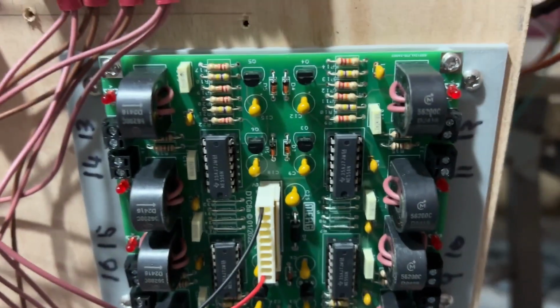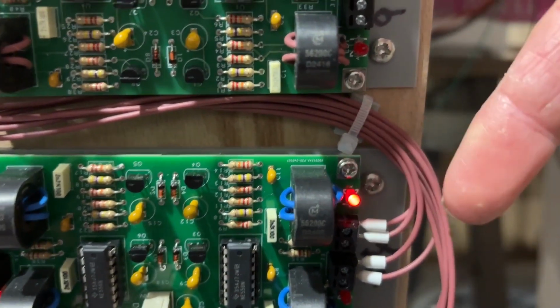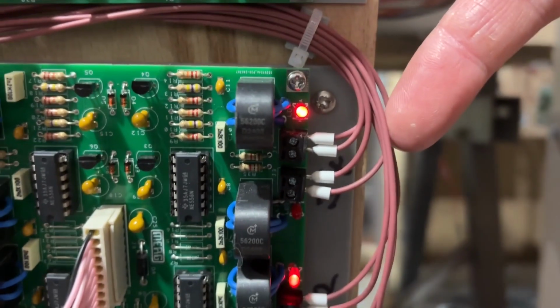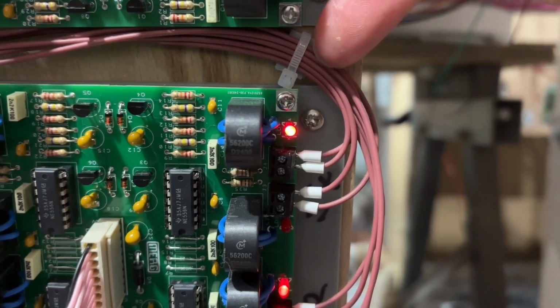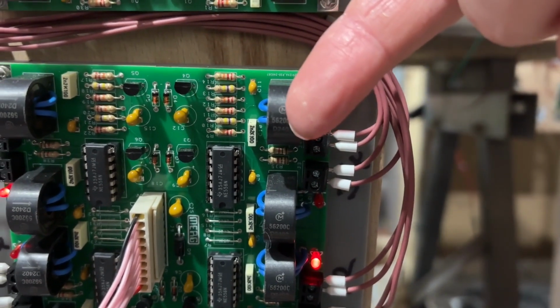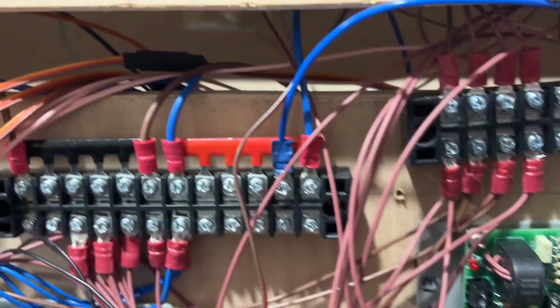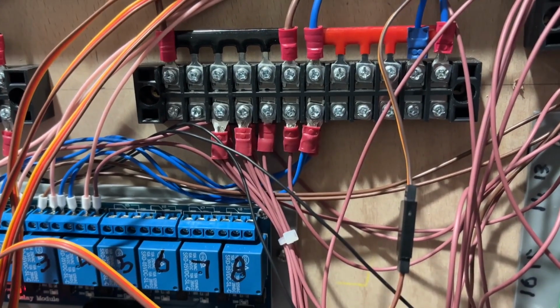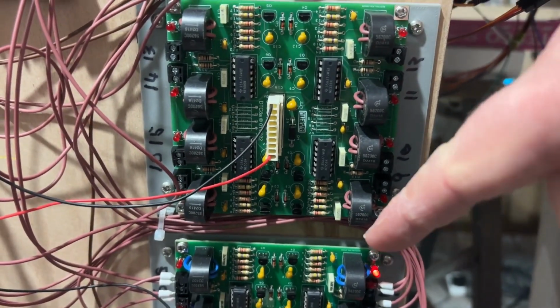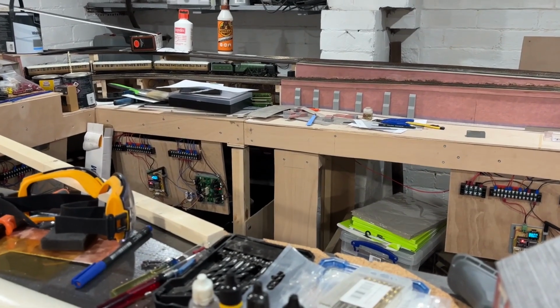And what we've got is a current transformer, which is what these little black things are. And at the side here are feeds. So one of the DCC feeds, in this case I use the brown wire, comes into one side of this coil, goes round and round, and comes back out again. One end connects to one of these messes up here, which gives it the power feed, and the other connects to the layout. So over there, there's a little board, and you can see there's a red light on.